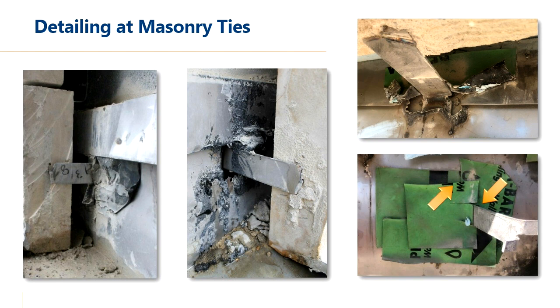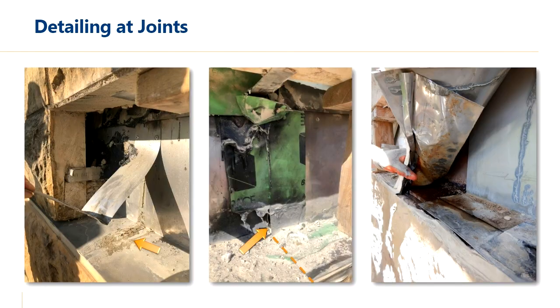At each of these penetrations for the flashing assembly, where the stone anchors are anchored back, we found significant voids. Here's just some images of them. Multiple materials were used, many different attempts, but for the most part, all of these ties had areas where water can enter the wall assembly and was entering the wall assembly.